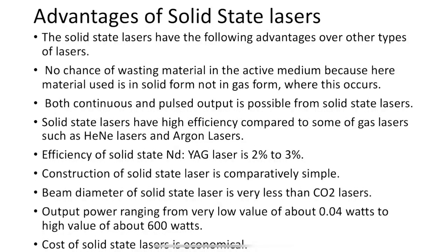So the advantages of solid state lasers. No chance of wasting material in the active medium, because the material used is in solid form and not in gas form where this occurs. Both continuous and pulsed output is possible from a solid state laser. Solid state lasers have high efficiency compared to some of the gas lasers such as helium neon lasers and argon laser. Efficiency of a solid state Nd:YAG laser is 2 to 3%.